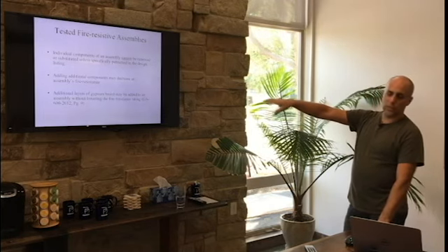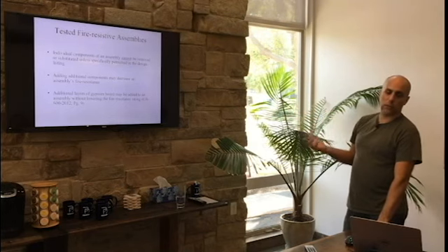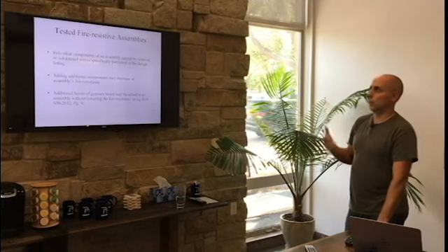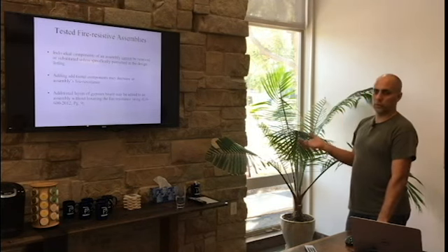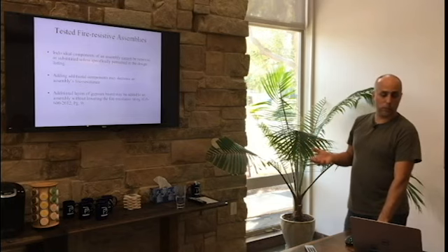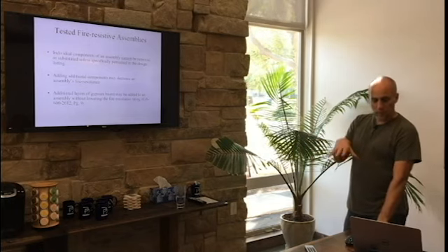Also, you can't just add anything you want to it. You can't go and add additional layers of some things. You can't go add some kind of flammable material to the inside of a rated assembly that's not otherwise permitted. It actually may decrease the ability.